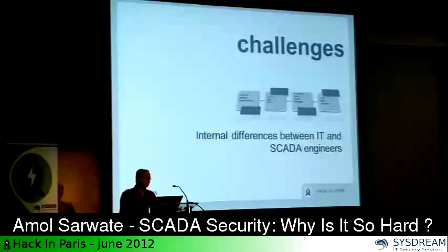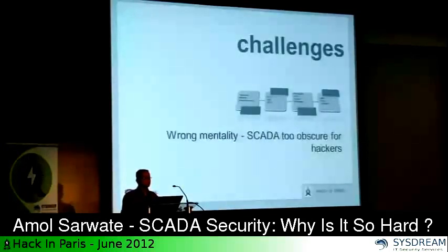I bring this out because if you are using any tool, even the tool that I am going to show you, please use it very cautiously. In any factory or any sort of installation, every quarter there is always a downtime. Use it there initially. Ask your vendor, if you are using a vendor's tool, whether they have tested the tool with the protocols, the PLCs, and the hardware that you have. Really push the vendor, since you are paying them for these tools, to make sure they have already tested it against your network.